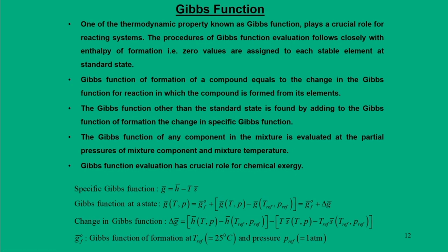The word Gibbs function comes into the picture when you deal with thermodynamic property relations, and in fact this Gibbs function has a very vital role in reacting systems. This information is similar to what we do for enthalpy. The Gibbs function of formation of a compound is equal to the change in the Gibbs function for the reaction in which the compound is formed from its elements, and this treatment is almost similar to what we do for enthalpies.